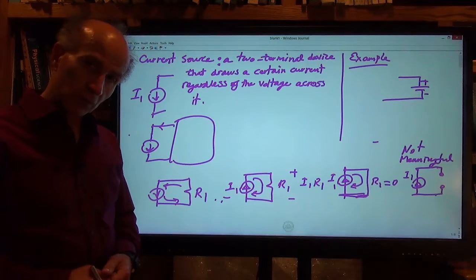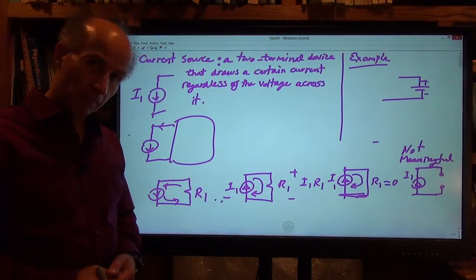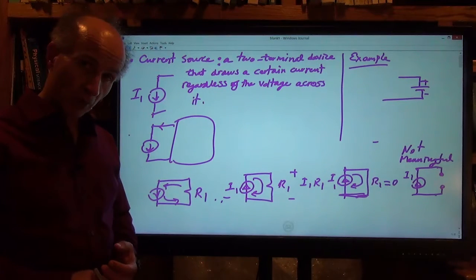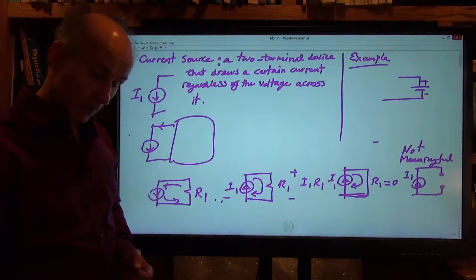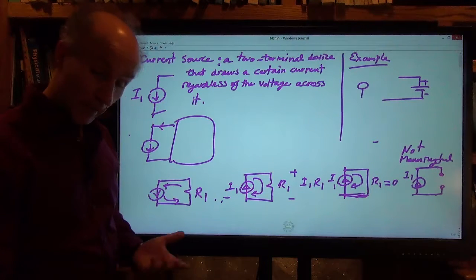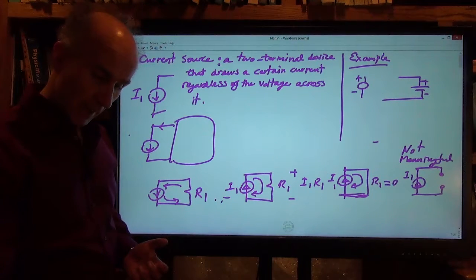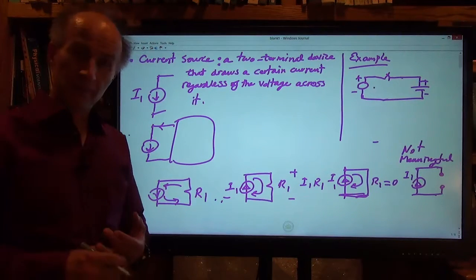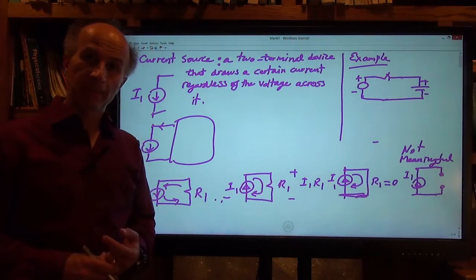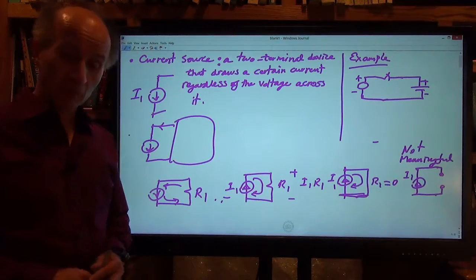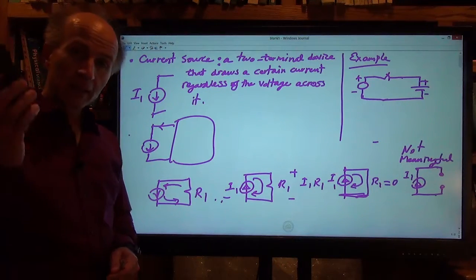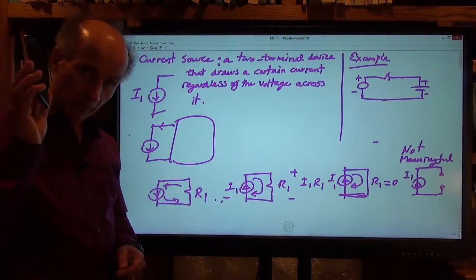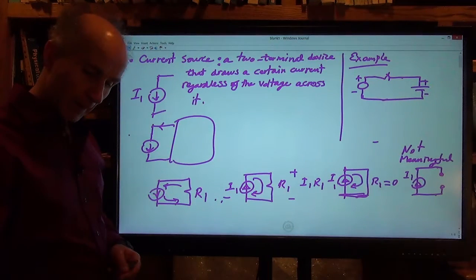Do I want to connect a voltage source to this battery to charge it? So here's a voltage source, another battery, right? And I just go ahead and put a switch here and connect them together. Would that do? No. That will dramatically shorten the lifetime of the battery inside the cell phone.